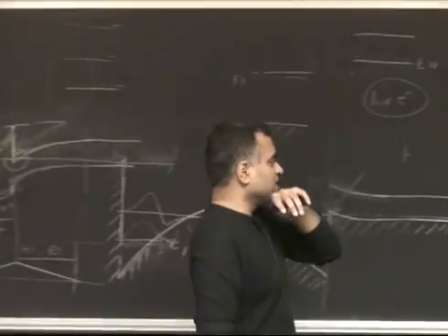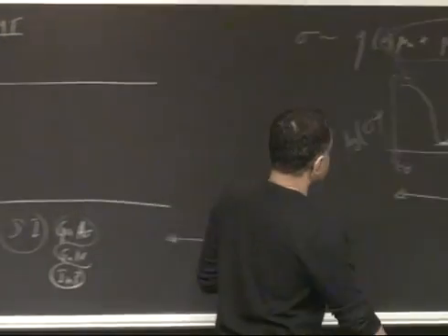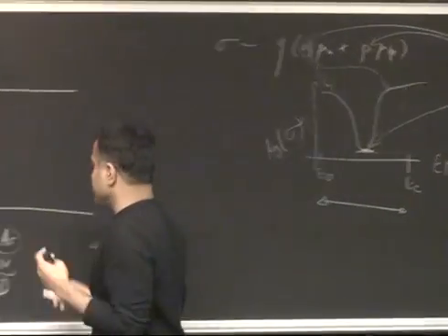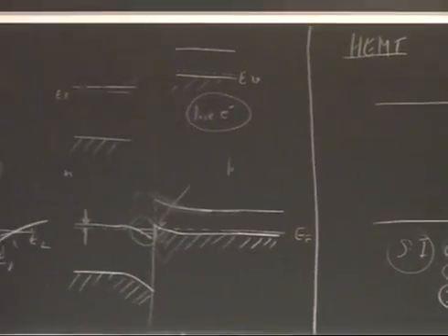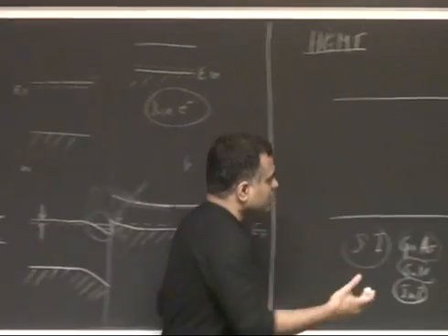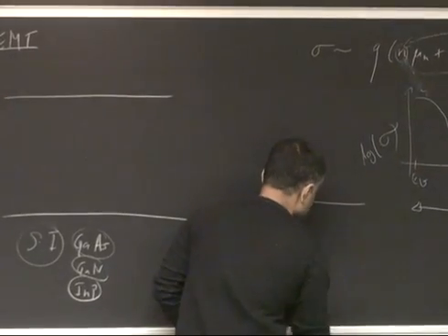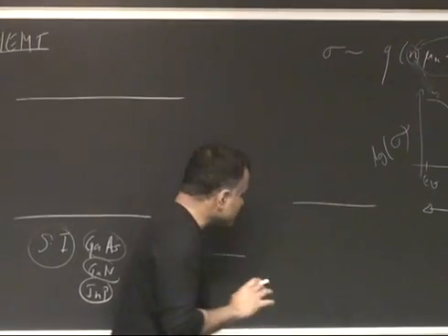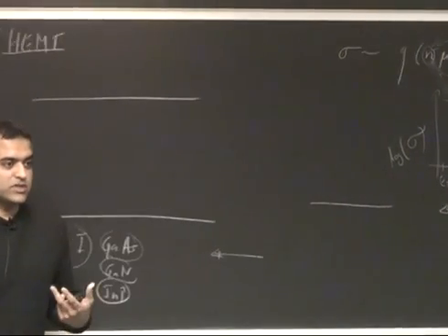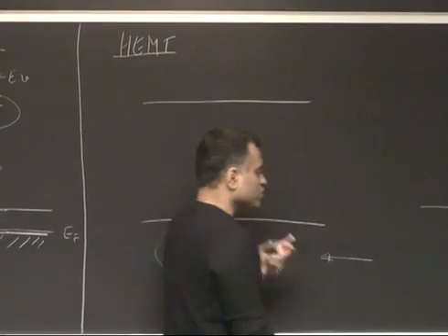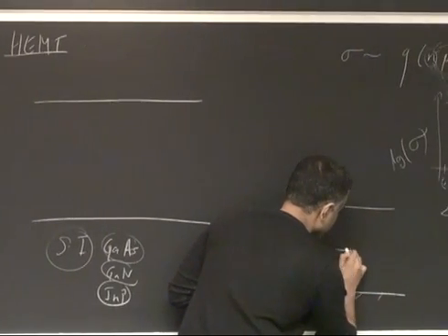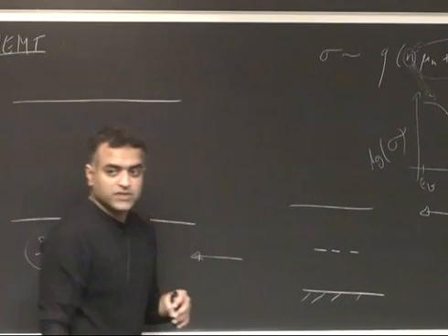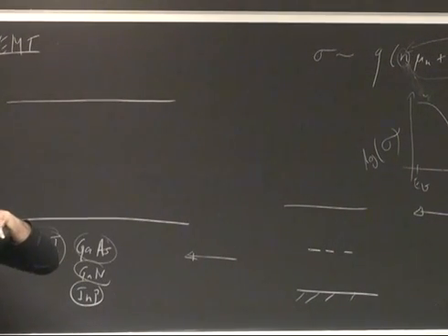So let's see. For example, semi-insulating gallium arsenide: what you do is, this is not purely gallium arsenide, and it's doped neither N type nor P type. Typically, one can grow it at a low temperature, sometimes called LT GaAs, low temperature gallium arsenide, or you dope it with something which introduces states very close to the middle of the gap, middle of the band gap.